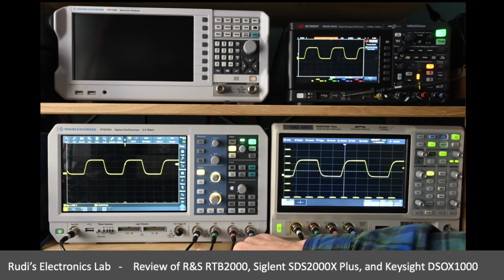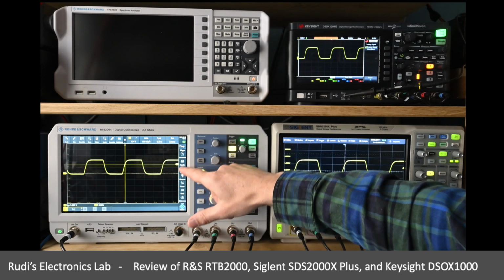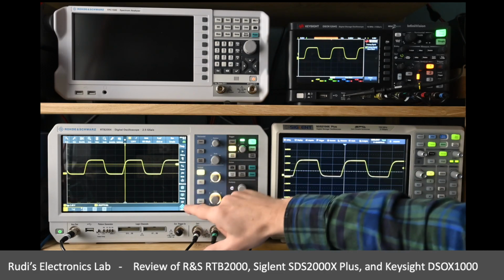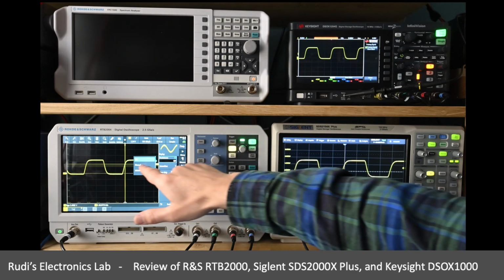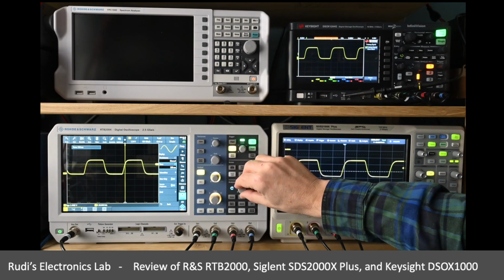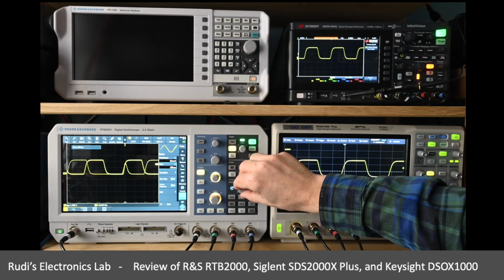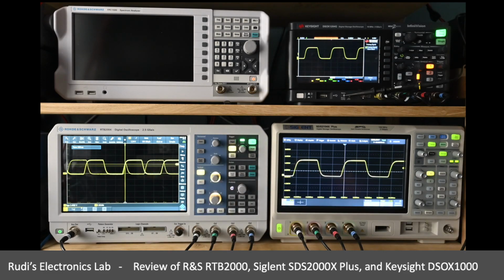So what I'm also going to do is use persistence mode, and to activate the persistence mode on the RTB device, we'll go to display, persistence, manual persistence, and then from the menu we can select different options, and I'm going to choose half a second here. Why half a second? I know my glitch is there about every second or so, if every glitch were being picked up. So by half a second I have persistence, but still will be able to see individual glitches here.